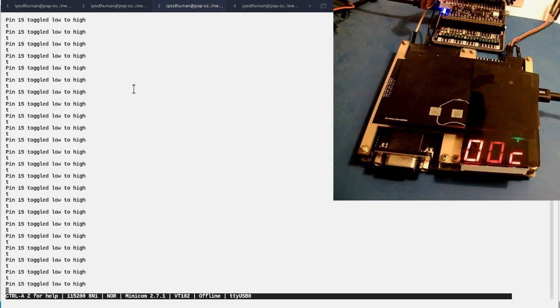And I can sit here and just tap the T key, toggling through, and it'll just sit there and count. Now the reason why we can actually see the interrupt counter, the blade's LEDs count, is because at 18 megahertz there is plenty enough time to get through some of the counting code of the 7 segment. That's how fast the 18 megahertz is that we're seeing.